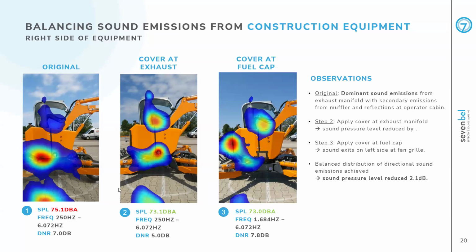Okay, thank you. What type and class of microphones are used in your device? In our device, and in most acoustic cameras, so-called digital MEMS microphones are used. These are highly compact microphones which have a very good signal-to-noise ratio and eigennoise level. They all come out of a semiconductor process, so they have very tight tolerances in terms of sensitivity. This is very important for an acoustic camera application, because in the end you want to acquire the sound field with microphones that perform equally and are identical to each other in terms of sensitivity and phase angle at different frequencies.